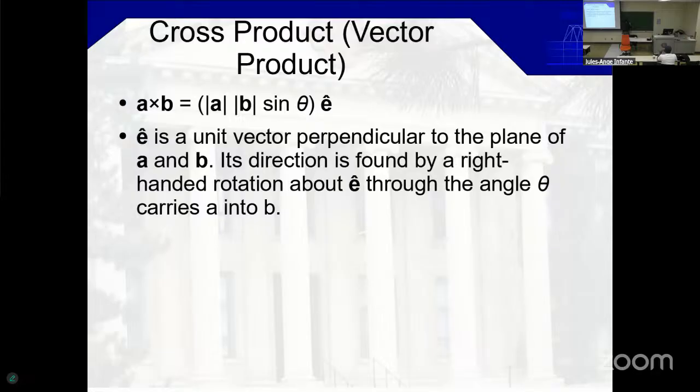So let's say I have the station and offsets, and let's say that I have these control points. It's on the median. Typically, you will have some control points along the center line of your roads, along the median. So I have here the easting of the first point and the northing of the first point. And here I have another for the end of the segment. I have another value for easting and northing.